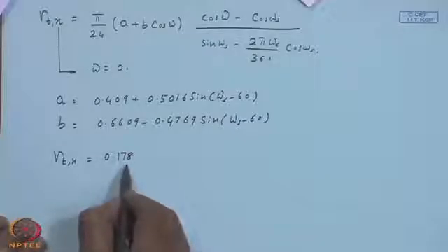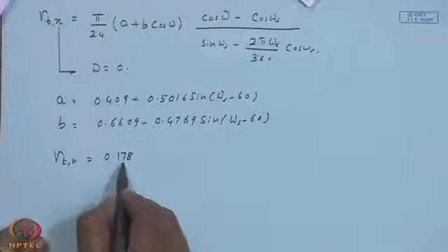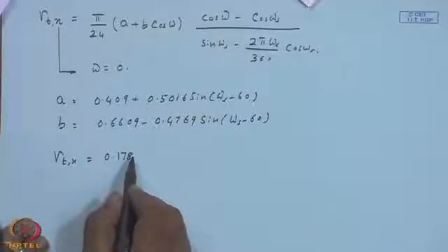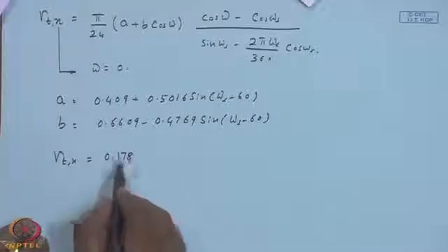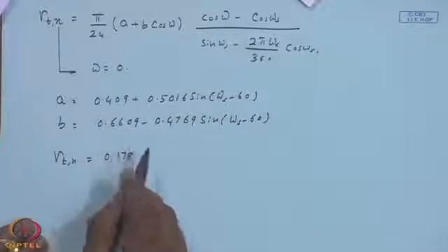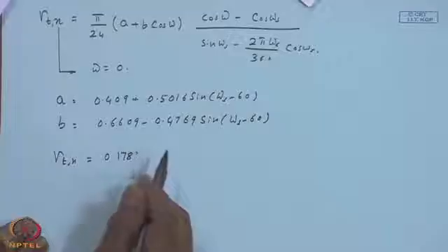So, R T n is 0.178. This is about the noon time, that means 11:30 to 12:30, and that is almost 0.178, meaning 20% of the total radiation. It can be expected, though it is only 1 hour, and the total hours are less than about 11 hours. Okay, 90 degrees corresponds to 10, 10 and a half hours. So, 20% can be expected in one single hour, because it is around the noon time.